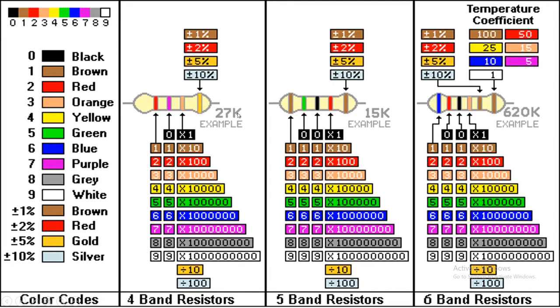You need to put 3 zeros, or K, because the second last number, as I told you before, tells you to put that many zeros. So the value of orange is 3, so you need to put 000. The last color is uncountable. It's telling us about the error chances. Here this color is green. The value of green is 5. It means this resistor has 5% tolerance up and down.